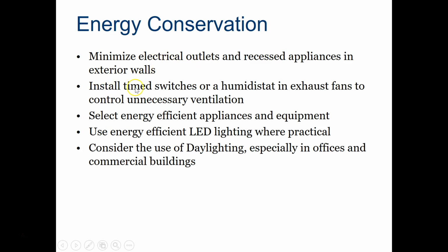You can install timed switches or a humidistat for exhaust fans in bathrooms and in kitchens and things like that, to be able to ventilate the building but not leave them on with just a switch and then somebody forgets about it. Select energy efficient appliances and equipment that's put into the house. Use energy efficient LED lighting where it's practical. And then we're going to talk about this more in the assignment, but consider the use of daylighting, which is something that you're going to learn more about, especially in offices and commercial buildings.